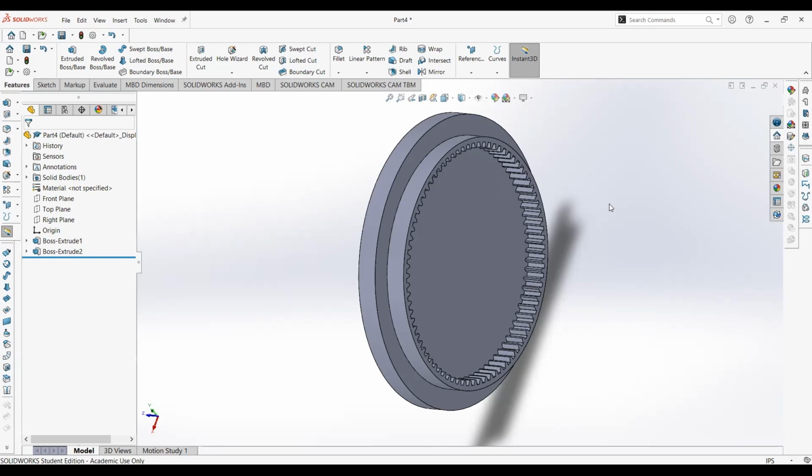What if you want to do the other features? Features, extrude, and you should have one extrude of the front and then another extrude of this back end. Everyone good on that? I'll give it 2 minutes and then let me know when you're ready to move on.